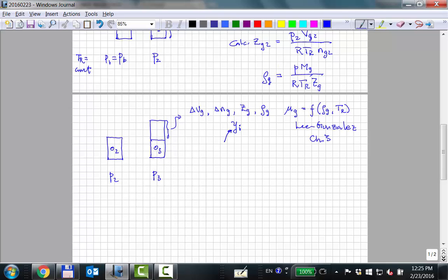So even if they report this, you should be a bit skeptical of the amounts of, let's say, the C5 plus heavier components that would form the condensate. Probably we didn't collect all of the condensate that fell out during the flash to standard conditions. Probably too low. So the gas that they report probably is too lean in a sense.